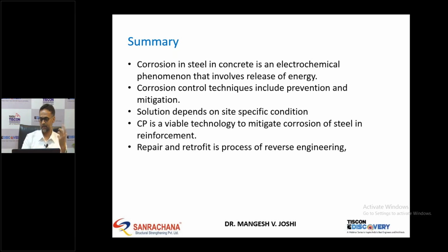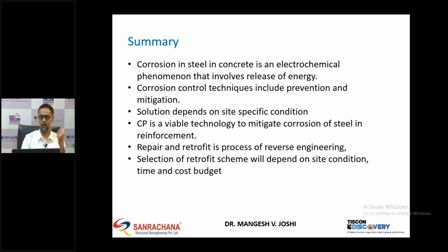Then we saw that repair and retrofit is nothing but a process of reverse engineering, and importance of starting the retrofit process from site rather than just sitting in your office. Then selection of retrofit systems is very important, and it will be governed by site condition, time, and cost in hand, and importance of structure. So these parameters will decide which retrofit system we are using, and accordingly we can choose different retrofitting system which we discussed.